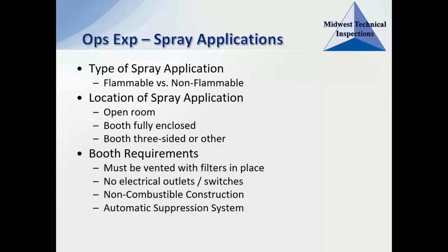If they have the manufactured booth, there are several requirements that we're looking for here. So the booth must be vented with filters in place. So we want a way of getting rid of all that extra vapor before it builds up and explodes. So they should have that ventilation system where the actual motor for the ventilation system is outside of the booth, but then it sucks the air out of it, whether it be a cross draft or a down draft or an up draft. There's some way of sucking the air through there and sucking it through filters so that it catches most of that overspray in the filters, so that it doesn't just pump it out into the atmosphere.